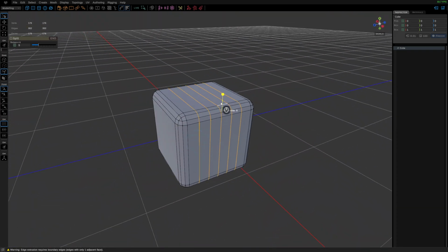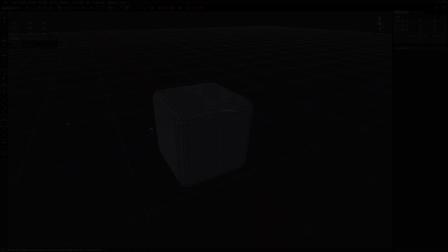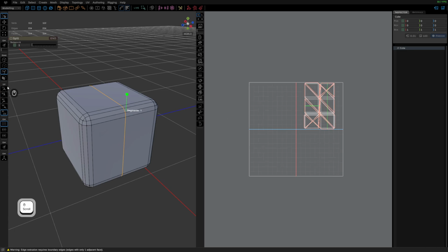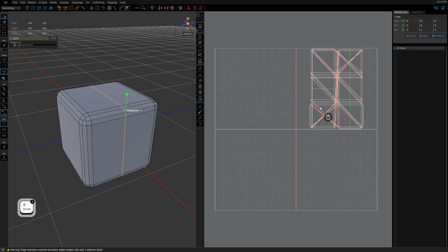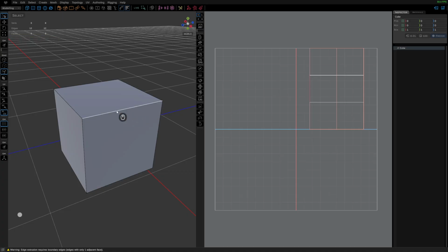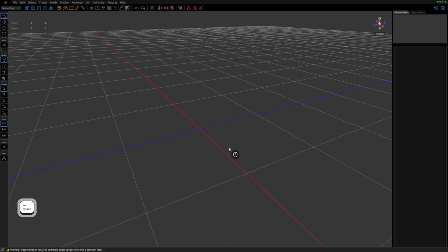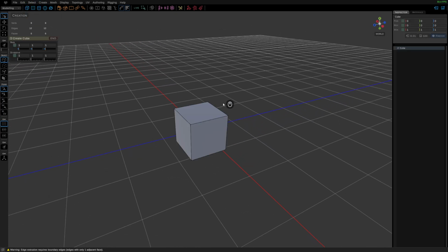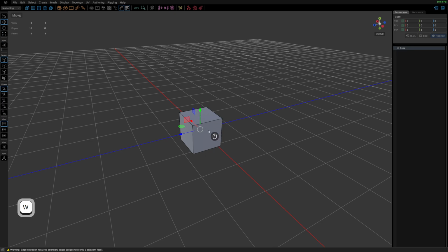This may be a good time to show how to enter UV mode. We can switch to a dual viewport here. The UV is a little messed up because we beveled the object earlier, so let's clean this up and start with a brand new cube. There we go. Now we do a split, and you can see that the UV remains persistent after the split. Next, let's do bridge. The shortcut for switching the viewport is also space. It returns to the last viewport, which is very useful.